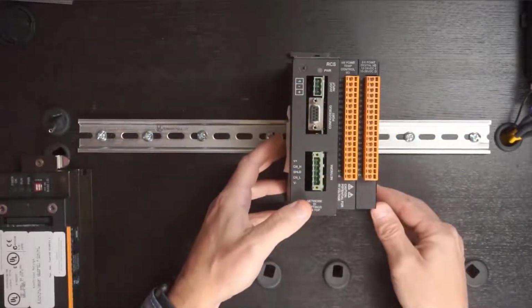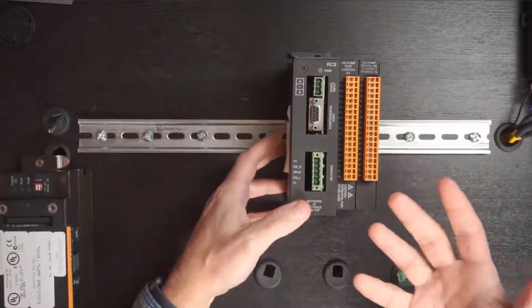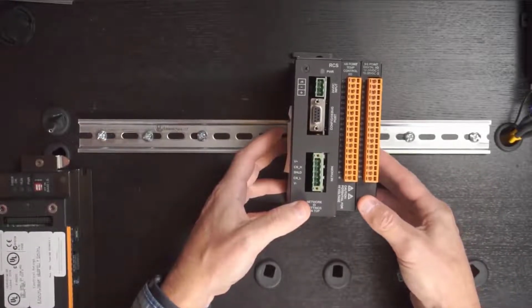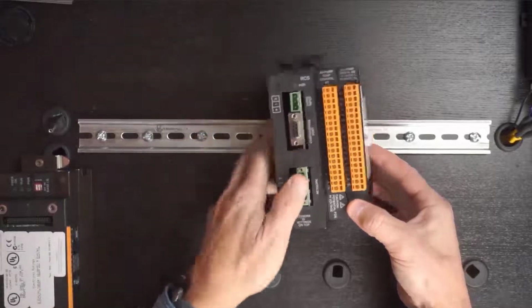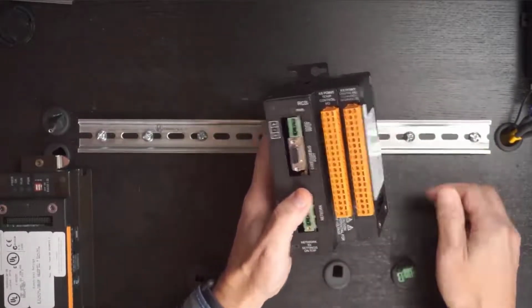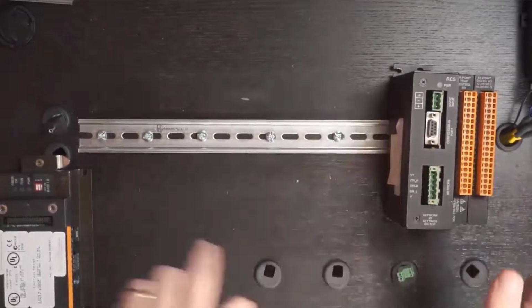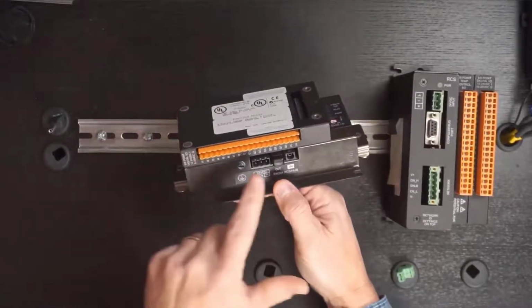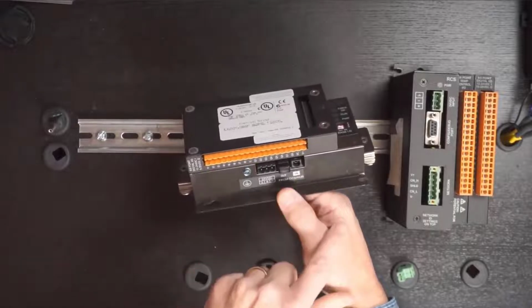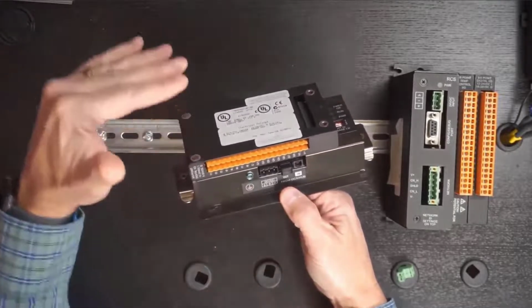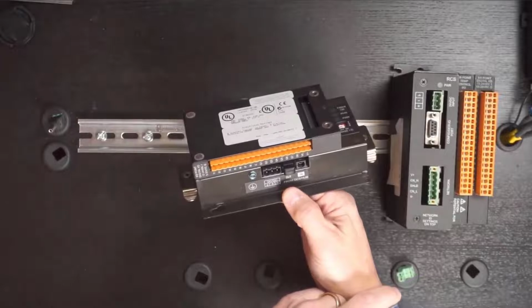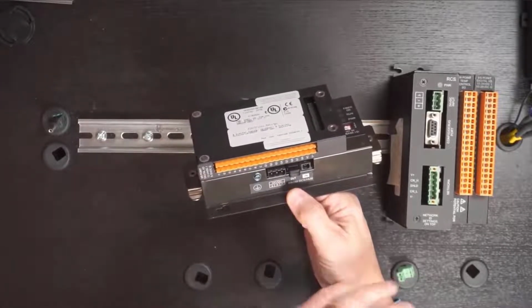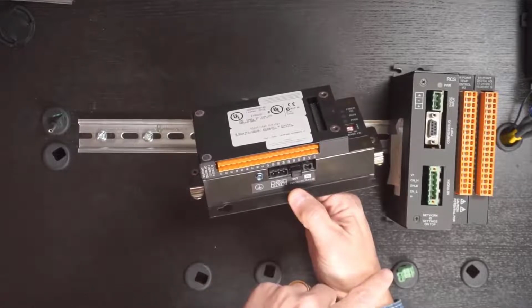Here is the RCS, which is effectively an OCS without a screen. It's often also used as a remote I/O block, and it's also metal and can support up to 4 modules. For a true remote I/O solution for SmartStack, we offered this remote fiber base. This one here interconnects with Toslink plastic fiber. You can have up to 4 modules plugged in on it, and you can have up to 5 of these bases on a system. The maximum distance that any base could be away from the OCS was 10 meters.